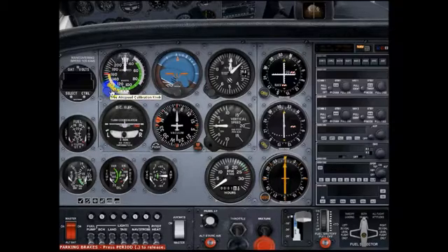So, talked about the white arc. The white arc runs from 41 knots to roughly 85. Then we have the green arc that goes from about 47 knots, slightly below 50, because we have 40, 45, 50, 55, 60, 65, 70, and so on. That's how it's calibrated. The yellow arc goes from 128 knots to 160, and the red radial line